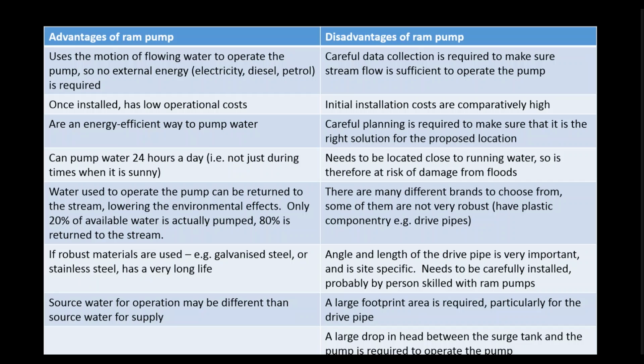That's actually quite a tricky thing to get, because often you may only get one or two chances to get flow data from a stream before you select, size and choose the pump. In reality, it would be really great to get data from the dry season and data from the rainy season, and maybe over a period of years, but in a lot of cases it's just not possible to collect that data before you have to size and design the system.